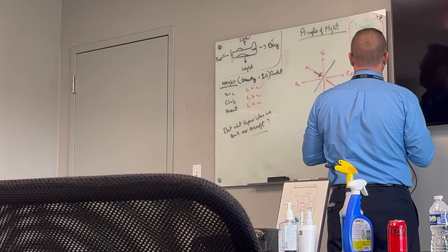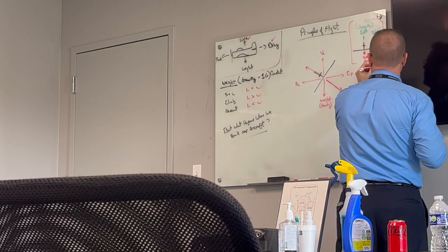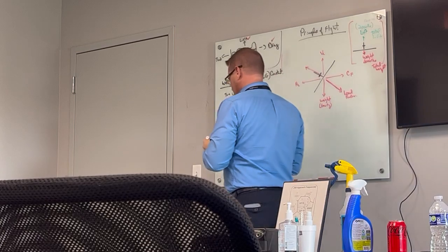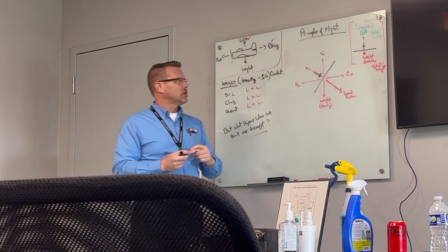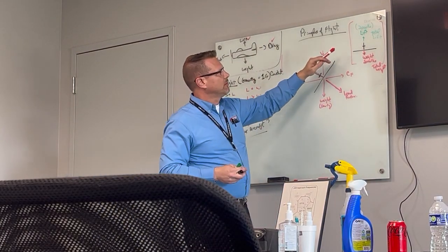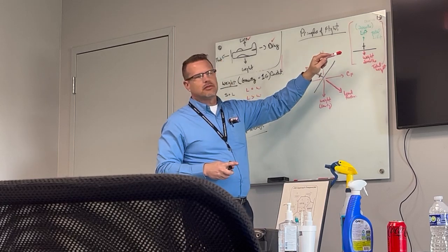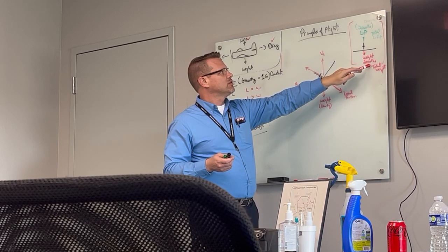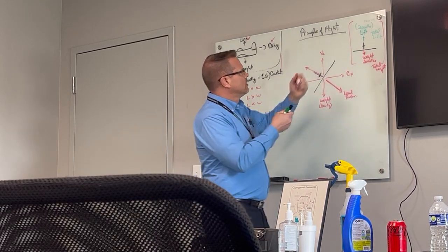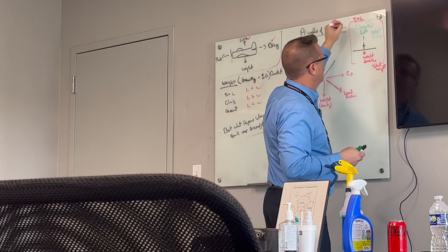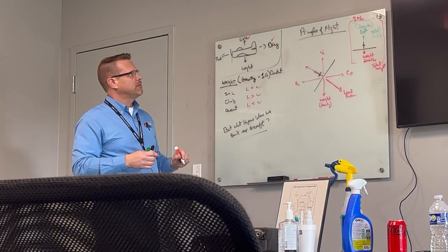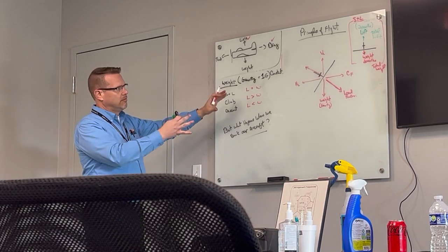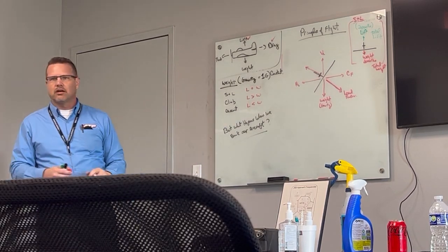And this is total lift. Okay. So I think the first thing is to go draw just a nice diagram. I kind of mentioned over here, but if I'm drawing my stick planes, I'm such a great artist, 2,000 pounds of lift. If I have 2,000 pounds of weight and we're straight and level, then I need to have 2,000 pounds of total lift. And what I'm gonna do is use those numbers to explain what happens when we bank an aircraft.